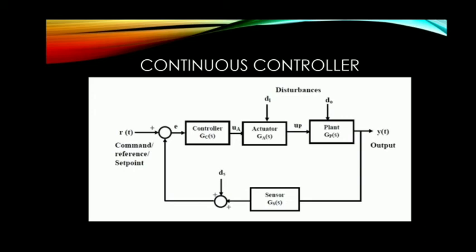Most industrial control loop command signals are piecewise constant signals that indicate desirable levels of process variables, such as temperature, pressure, flow, level etc., which ensure the quality of the product in continuous processes. In some cases, such as in case of motion control for machining, the command signal may be continuously varying according to the dimensions of the product. Therefore, here deviation of the output from the command signal results in degradation of product quality.